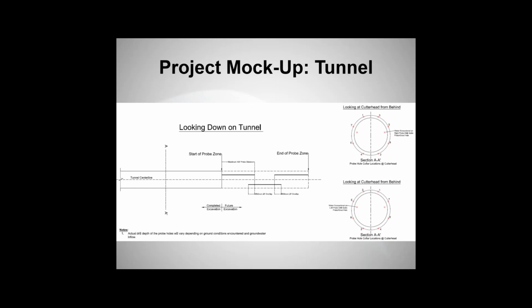And so, for this example, it's like, here's a submitted probe zone overlapping, how are we going to probe? We know what the triggers are. If we have groundwater inflow through this probe zone, this is the sequence that we're going to grout the machine. If we have groundwater infiltration and grouting is triggered from there, this is how we're going to alter the grout injection sequence.